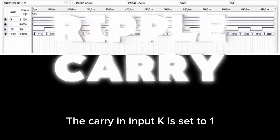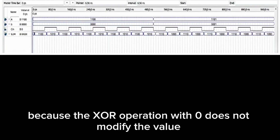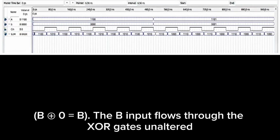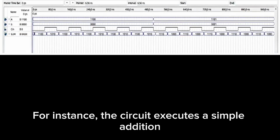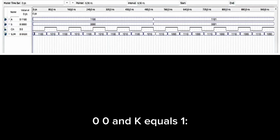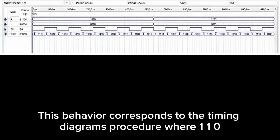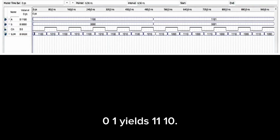The carry-in input K is set to 0 when the circuit functions as a 4-bit adder. Because the XOR operation with 0 does not modify the value, B0 equals B, so the B input flows through the XOR gates unaltered in this mode. For instance, the circuit executes a simple addition if A equals 1100, B equals 0000, and K equals 0. 1100 plus 0000 equals 1100. The output stays at 1100 because the final carry-out is disregarded. This behavior corresponds to the timing diagram's procedure, where 1101 plus 0001 yields 1110.